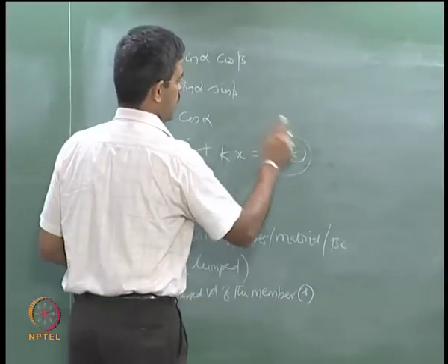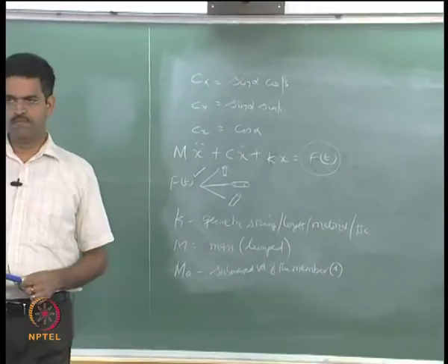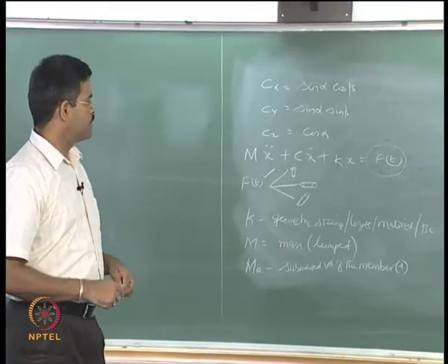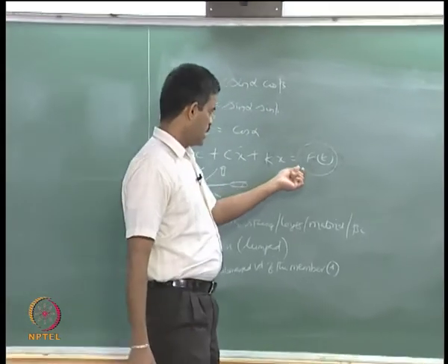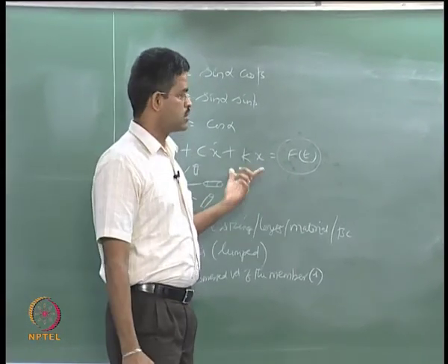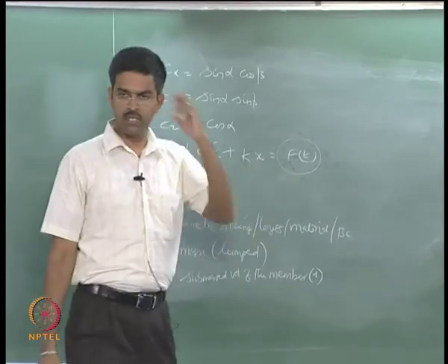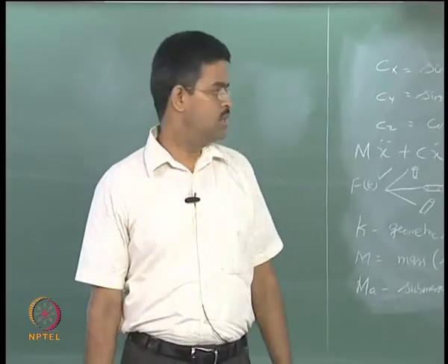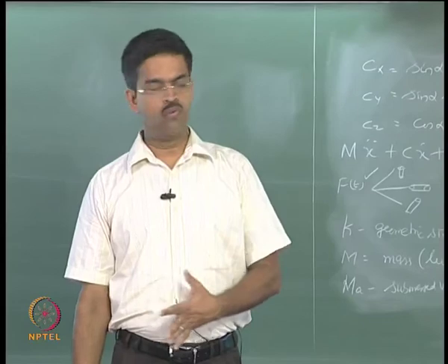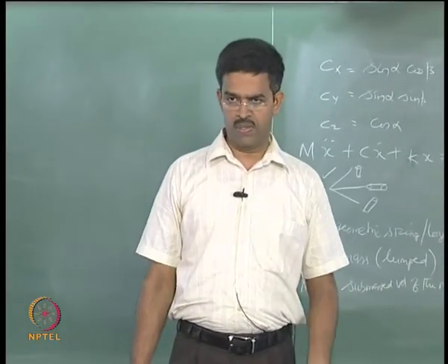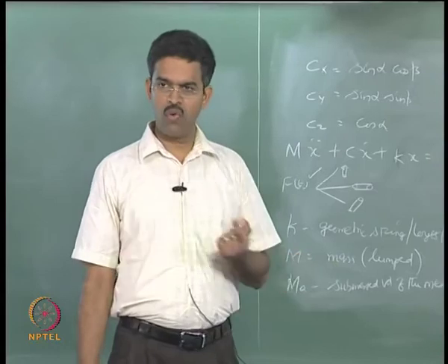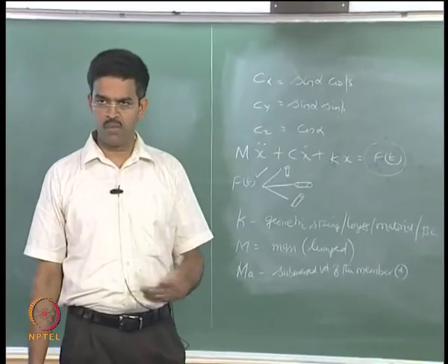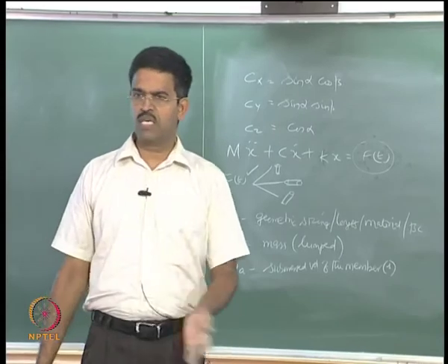Now, the argument comes here, as I explained in the previous lecture: if an earthquake force also acts on a given system, how do I model this? How do we account for the earthquake or the ground acceleration on the system? There are two cases here. As far as fixed jacket structures are concerned, these structures rest on the seabed, resting on piles, etc. So, the direct force of ground acceleration can be applied on this. How to handle this? If they are floating, if they are anchored to the seabed by tethers or some other systems, then how is it transferred? Both cases we will handle.